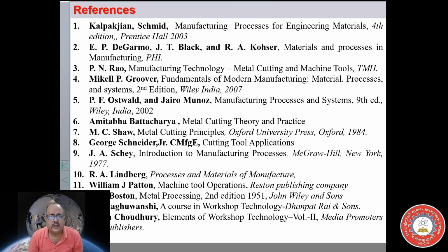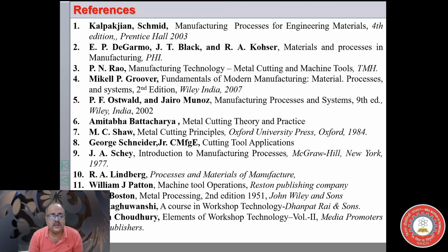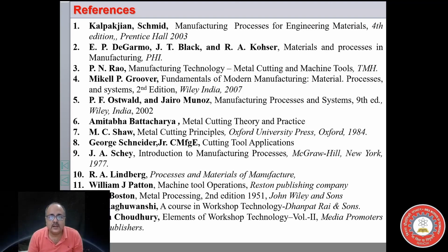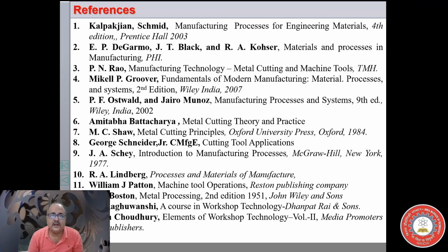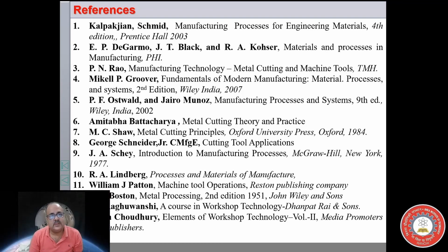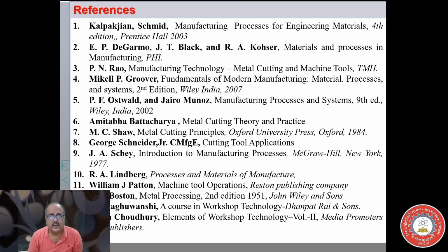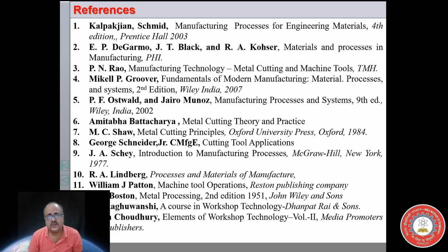I hope the geometry of single point cutting tool, which is a very complex geometry, is clear. And I would recommend, if you are good in CAD modeling, 3D modeling, try to model a single point cutting tool. You will find it extremely difficult because each plane is inclined at 2 angles. So it is very, very difficult. So try to do it. This will clear your concept also. And I hope you understand how to designate a single point cutting tool in American Standard Association system.